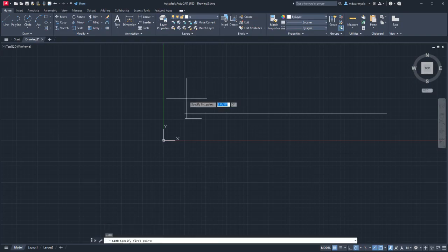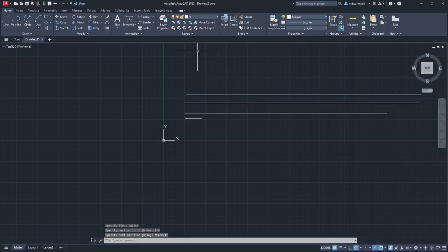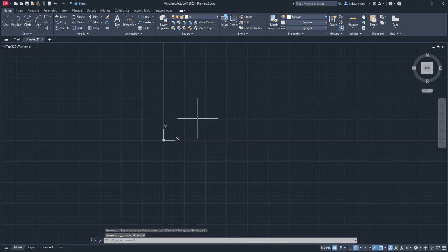If I want to draw it in feet and inches, just out of preference, I usually do 2 feet, and then put the inches on it, and it'll draw it out to there correctly. But I don't think you have to do it every time. If I just do 2, 4 without the inches, you can get that. So you don't have to put inches down because of that setting.